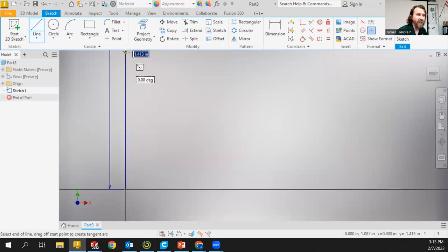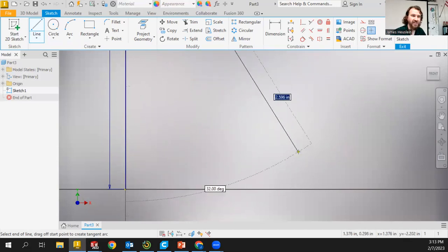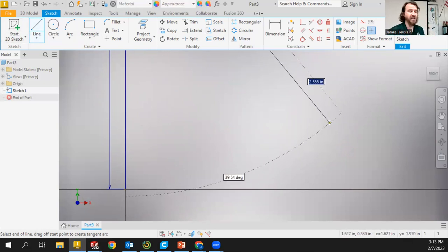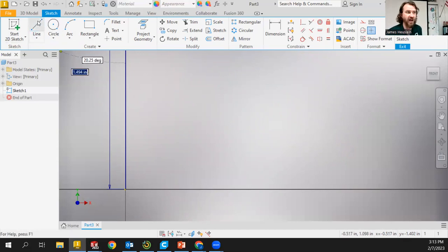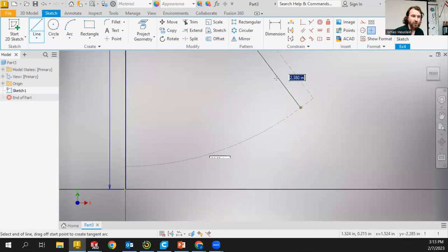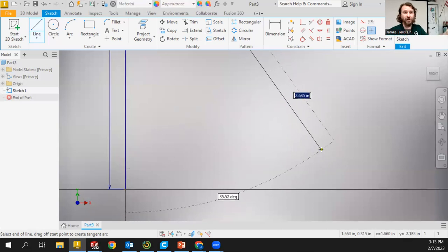And my line goes way out of screen. So I need to, again, adjust my visual frame of reference here. The easiest way to do this at this point, I'm still in the line tool. I haven't exited. I haven't hit the escape key. I've just made one line and hit enter. And Inventor is saying, oh, you want to make more lines. So they're keeping the tool open. You can see it highlighted here in the ribbon. And we can see that we're still in sketch mode with the green checkbox. And we can see right here, we're bringing a line down that comes off screen somewhere, and it's coming down towards our screen here and has a length of 2.612.